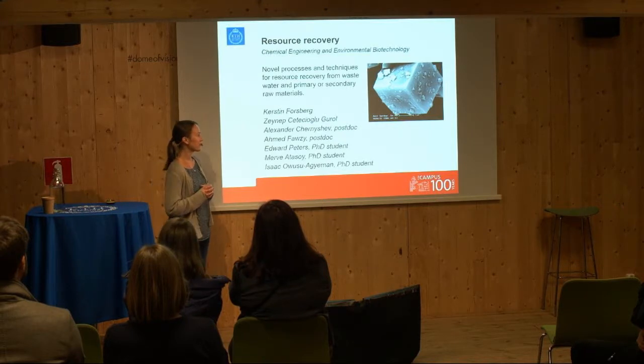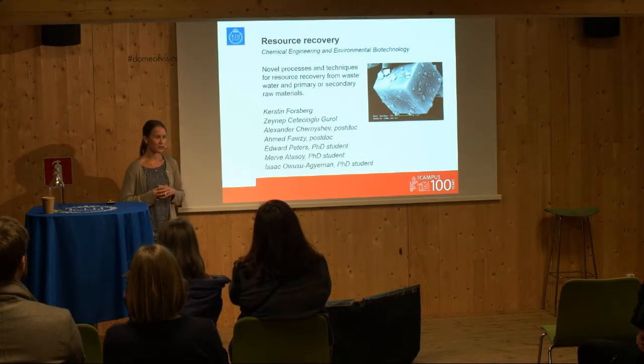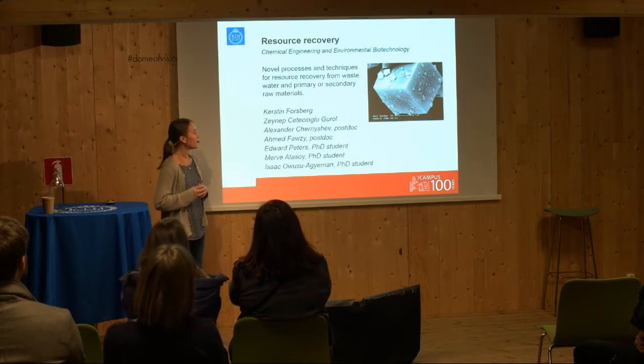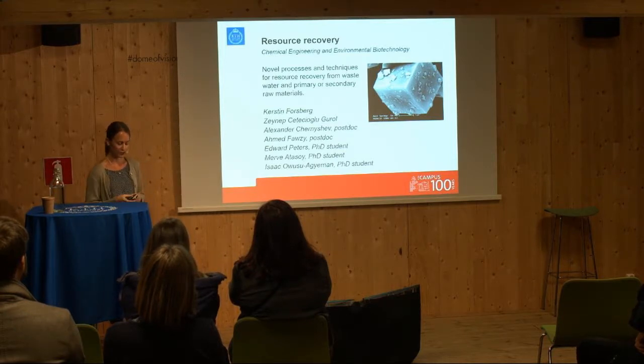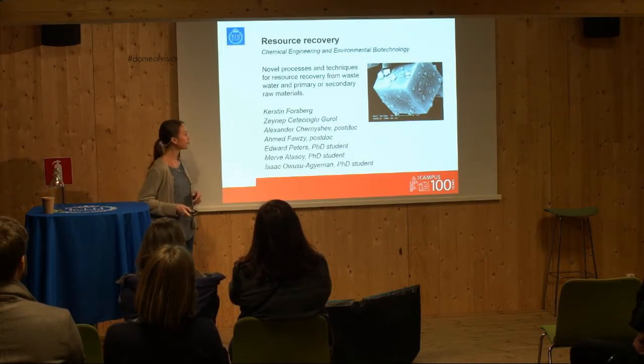And this was a project in collaboration with IVL, the Swedish Environmental Research Institute, located just here next by. And we developed a process combining nanofiltration and crystallization to separate out the metal ions as metal fluoride hydrate crystals, so that the acid could be reused, and also we could get some value from the metal content. So it's a nice example of a project on resource recovery.